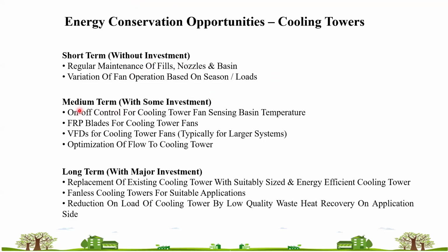A VFD with a feedback-based system is majorly a good system for a cooling tower. Then FRP blades, then optimization of flow to the cooling tower. These are some medium-term investments. Then long term is replacement of the existing cooling tower with a suitably sized and energy efficient cooling tower.